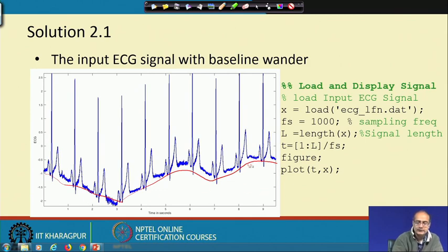So, this phenomenon is called baseline wandering, and as it is moving much slower than the ECG wave, we realize it is a low frequency noise or low frequency artifact. And now, we need to take care of how we can actually clear this.